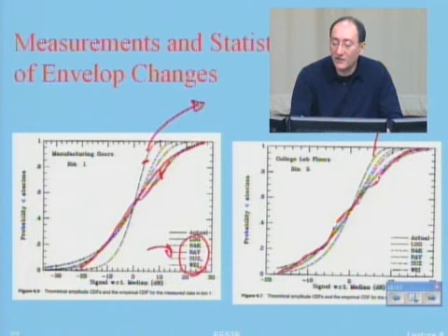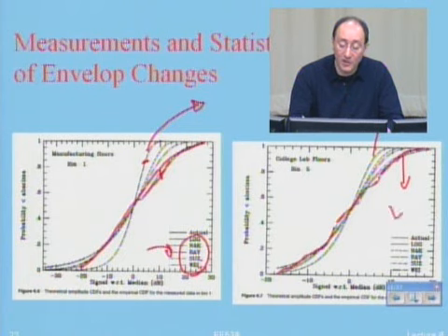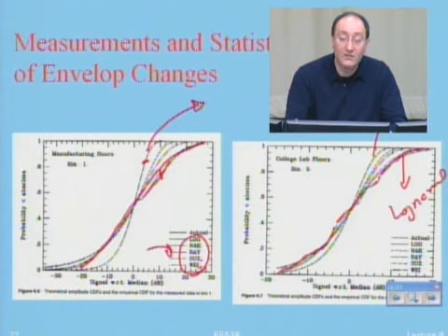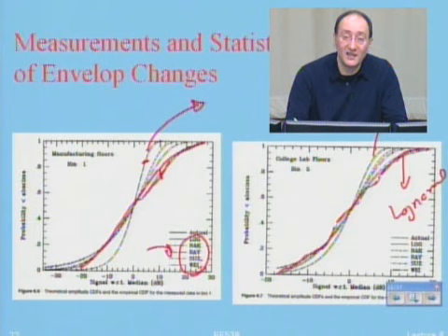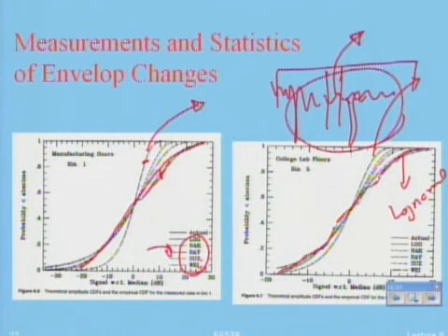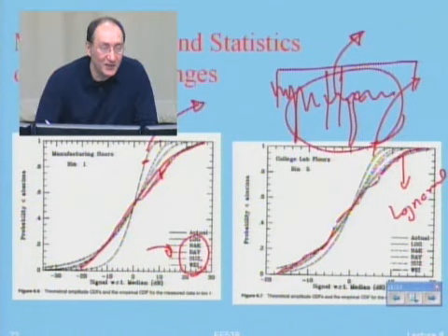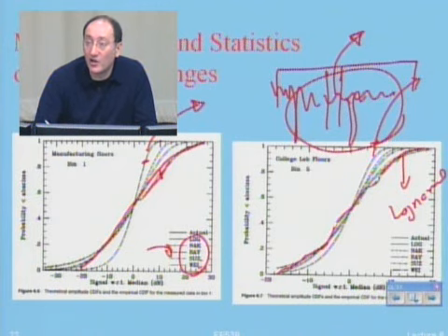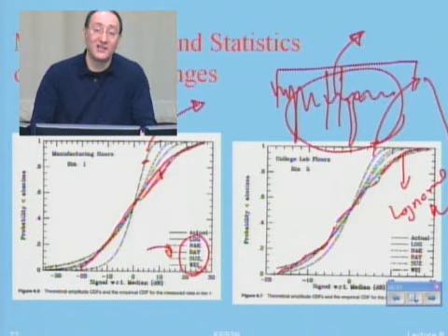And what do they fit? They fit the log normal best. Why? Because log normal is shadow fading. The channel in the frequency domain is something like that. If I have a bandwidth like this, this is Rayleigh. But if I take a bandwidth like this, I'm averaging the Rayleigh fading. It's no more Rayleigh anymore. What is that? It's shadow fading. What is the statistics of shadow fading? It is log normal. And this is something very advanced today, actually.